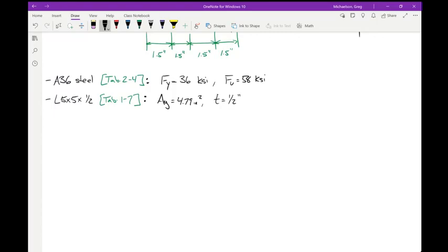If the lower bound for Fu, we wouldn't use it for axial design. The recognition of the upper bound is more for ductility concerns that happen in earthquake land. In earthquake land, you're putting the structure through a very large degree of lateral translation. It's undergoing a lot of deformation, so understanding the ductility is very important. But to be clear, earthquake engineering is kind of a whole other animal in and of itself, in the way that you approach it and the way that you handle it.